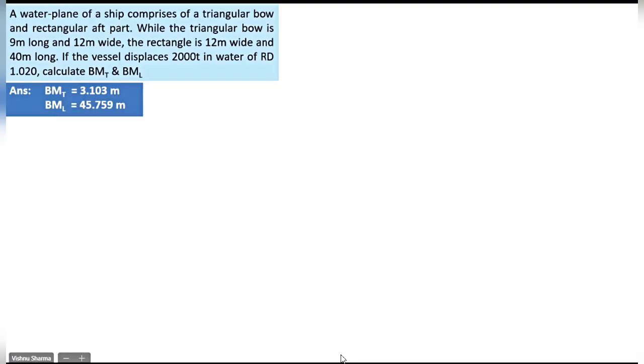Now we'll come to combination of shapes, beta. And moment of inertia will be reinforced. You don't have to run after too many exercises. Don't worry. Look at this. Guys, for this particular case, read the question and try to make the water plane area. What will be the shape of the water plane area? Draw the water plane area, please.